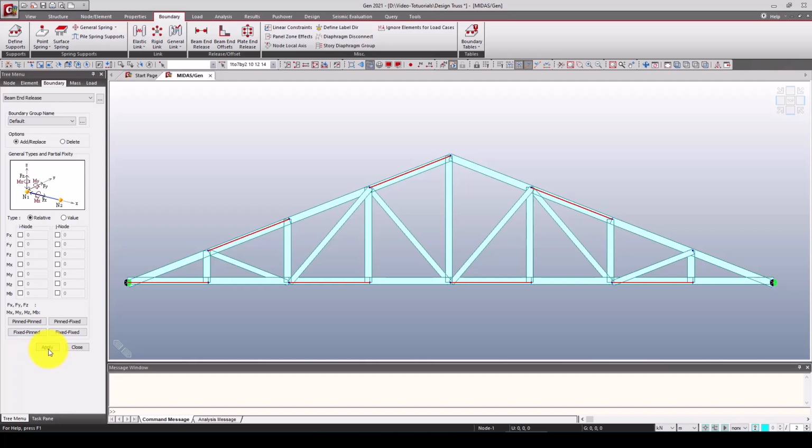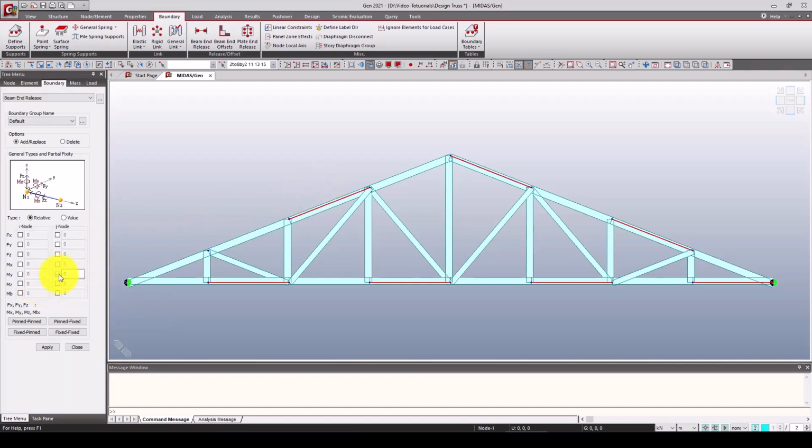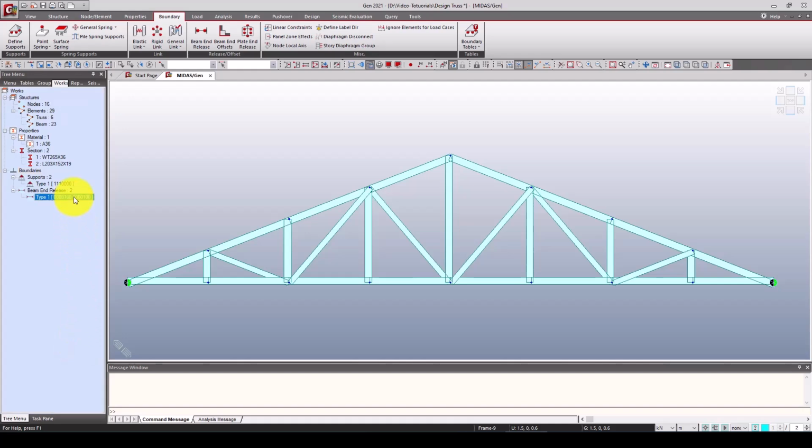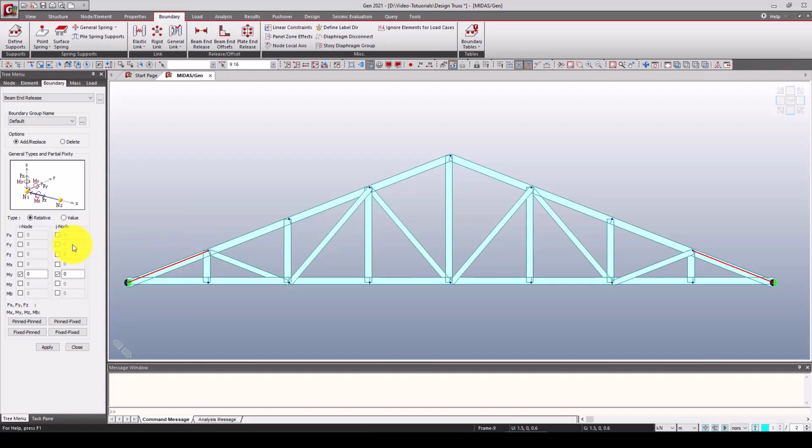So I'm going to add this is fixed, so no need. And the second is also, I'm going here to see this also shouldn't have any releases, because the top chord is directly fixed. So the only releases allowed are in the diagonal and vertical members. The last one here is going to be what's going on here. So this also should be okay.